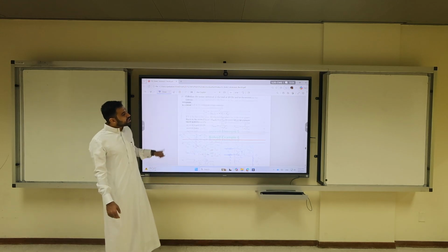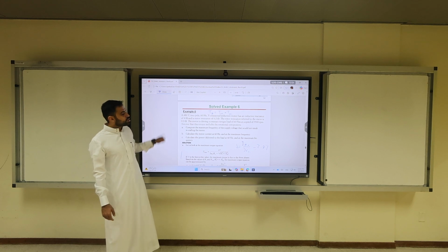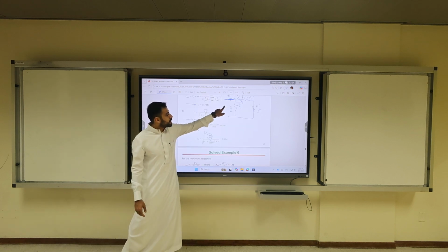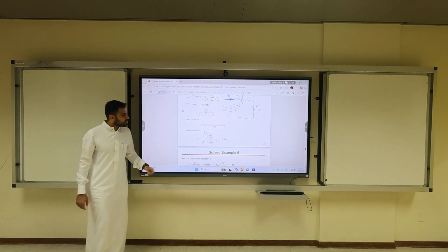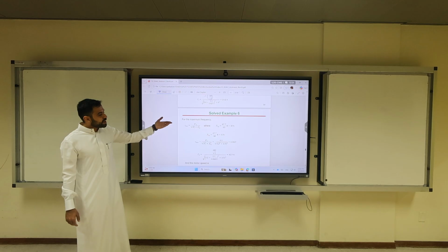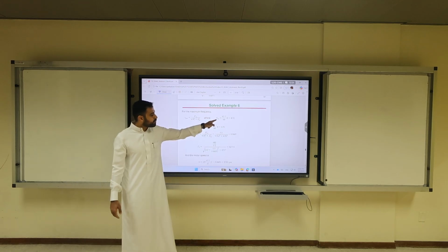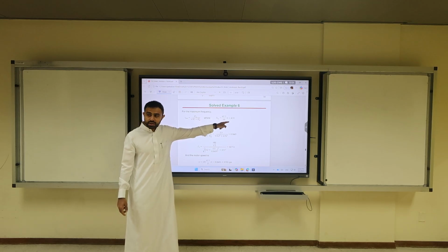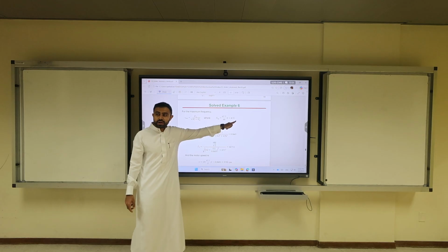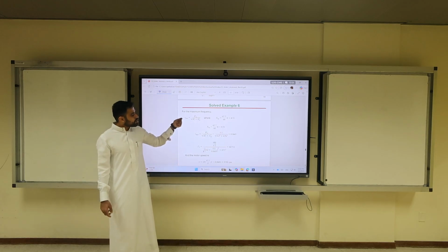In the previous example, is XM given? If it's not given, you can assume it's very high. So this is very high. It's not given, just ignore it. Go back to the 67 Hertz. What do you need to do? You need to readjust your X equivalent by multiplying it by 67.7 over 60 times 4. This is the new quantity, 4.51 ohms. You also need to calculate the new slip.